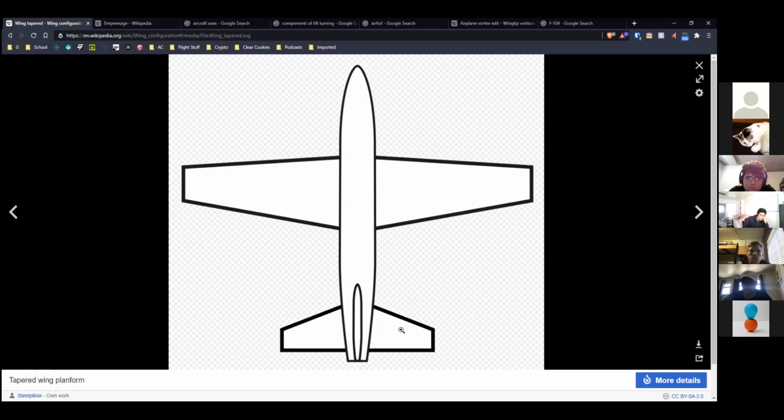The same thing applies here. If the center of pressure on this surface is in front of the middle of its attachment, then the air can catch the surface and push it farther and farther away from neutral. Whereas if you put the center of pressure behind the attachment point, then the air will be a restoring force.